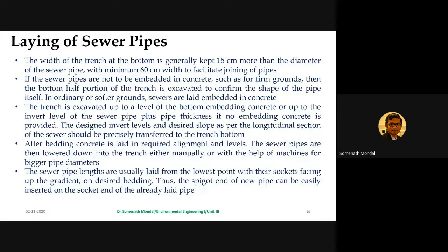The trench is excavated up to a level of bottom embedding concrete, or up to the invert level of the sewer pipe plus pipe thickness, if no embedding concrete is provided. So this is another important point which needs to be remembered. The designed invert levels and desired slope as per the longitudinal section of the sewers would be precisely transferred to the trench bottom. This is also very important for the smooth conveyance of the sewage.